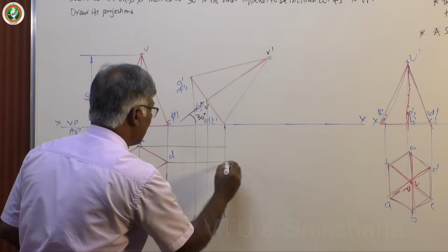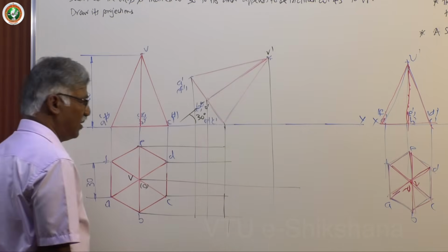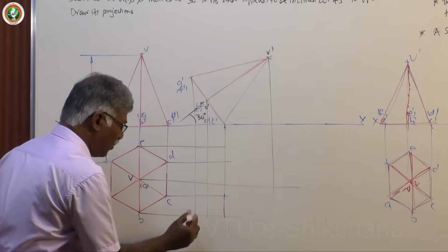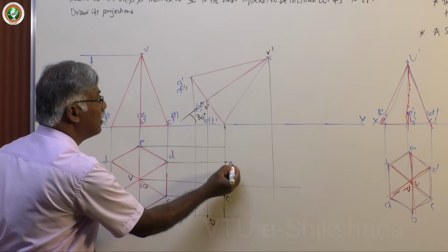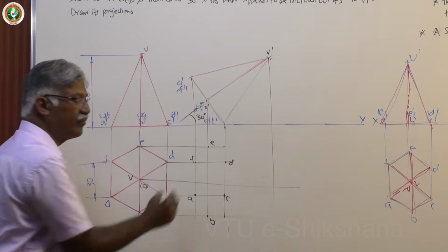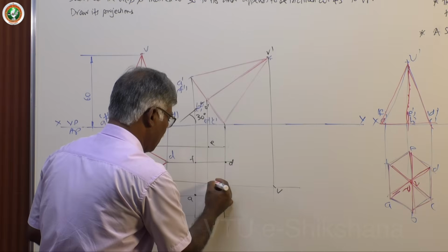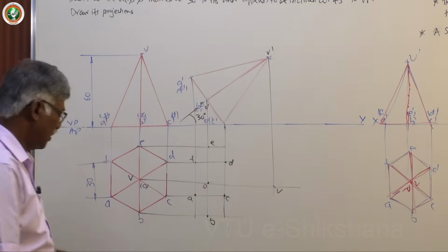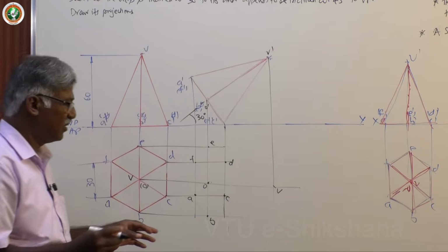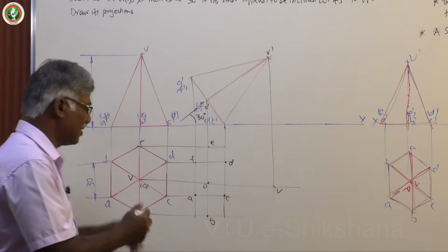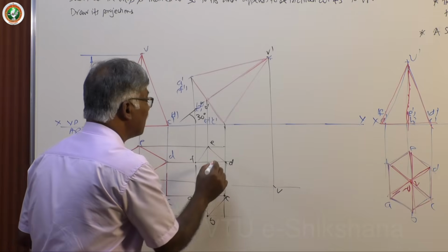So let me project these points, and the apex point project up to this and draw again. Now it's easy to identify. This is A, B, C, D, E, F, base points. Then this is O. Now visibility of all the edges, whether slant edges or base edges. Let us see. Join all these points with light lines first.